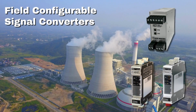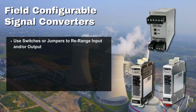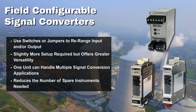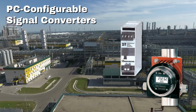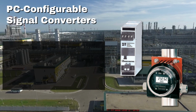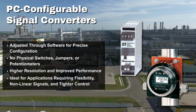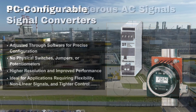A field configurable signal converter, on the other hand, allows you to rearrange inputs or outputs using switches or jumpers. It takes a little more setup, but this flexibility means one device can handle multiple applications, reducing the number of spares you need on hand. Finally, PC configurable signal converters offer even greater flexibility, precision, accuracy, and control. They allow fine-tuned range settings and software-based adjustments without physical switches or jumpers. In addition, they can easily handle reverse output, split range, and custom linearization scenarios.